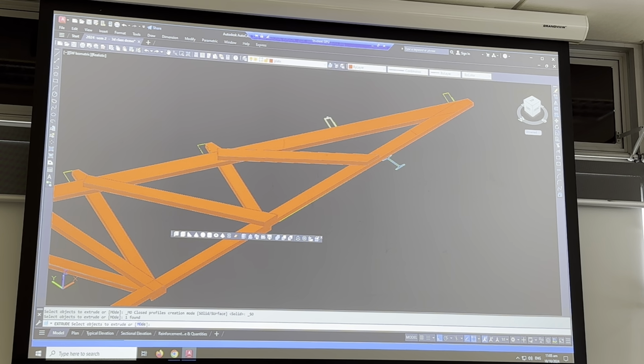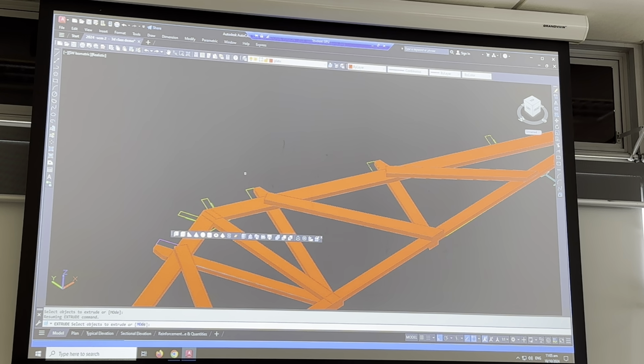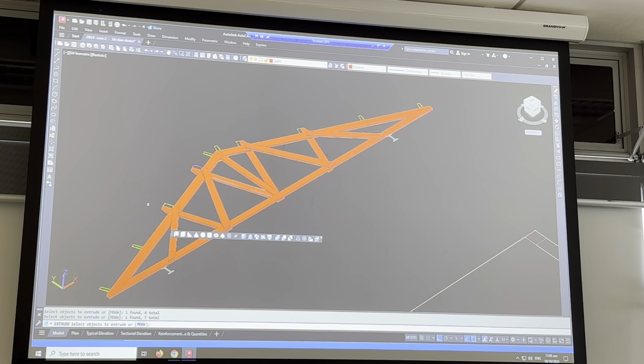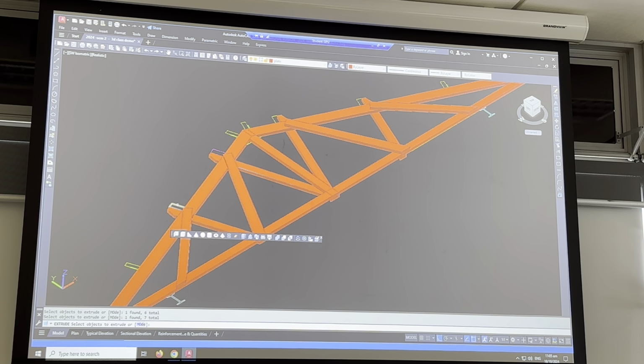Roger, according to your drawing, the two purlins closest to the eave, that run alongside the eave, actually extend beyond the frame, but the ones closer to the ridge are flush with the frame. So the end ones are a bit longer, it looks like. I'm okay if you just make them 6'8".